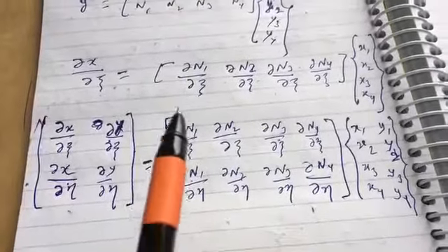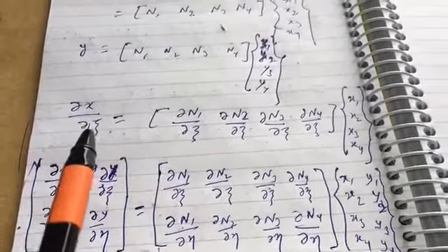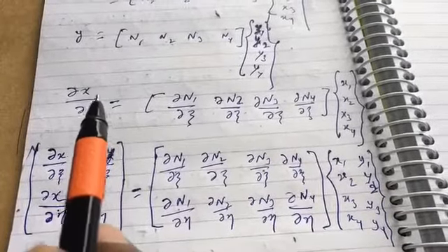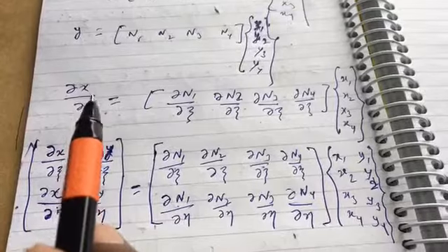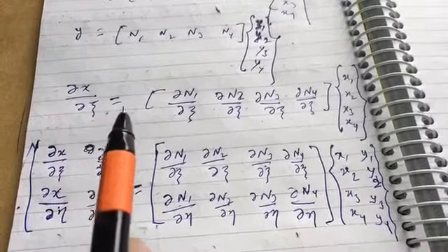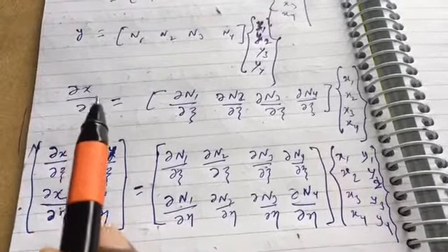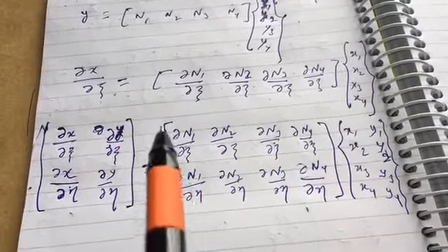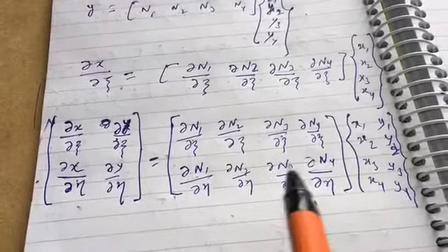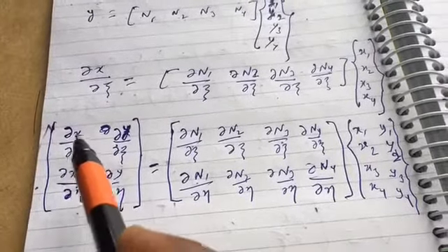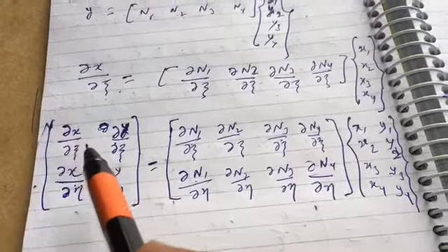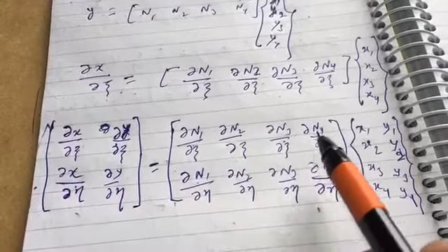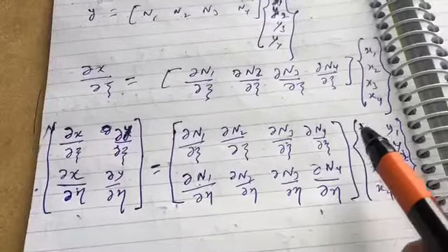So we have combined it. This is just for one example, and we extend it further by replacing xi with eta, and x with y. So we have this combination. If you want del x over del xi, then we have this row multiplied by this column.